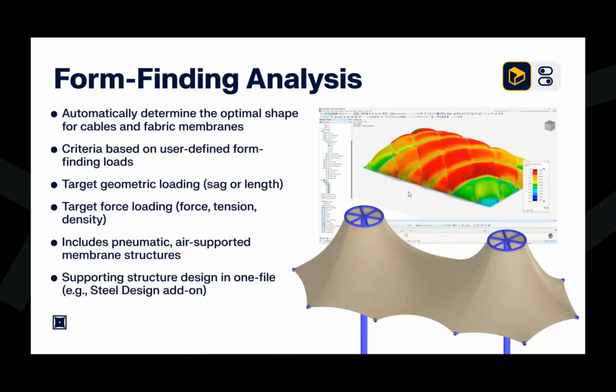So it's quite common with these fabric membranes that we have steel members as well. So being able to carry out the full steel member design according to the AISC or the CSA standards, and not having to use a specialty program for the fabric, manually transferring these forces into another program that carries out the steel design, but everything is carried out together.